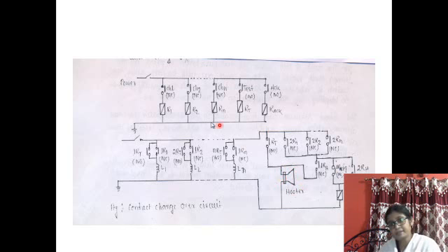Once again I am trying to explain. When the channel fails, R1 is in de-energized state. That's why this contact is in closed position. Similarly, this is a similar NC type contact for this relay, so this will also close the circuit, and the power, this is the power line, will flow through this closed path.